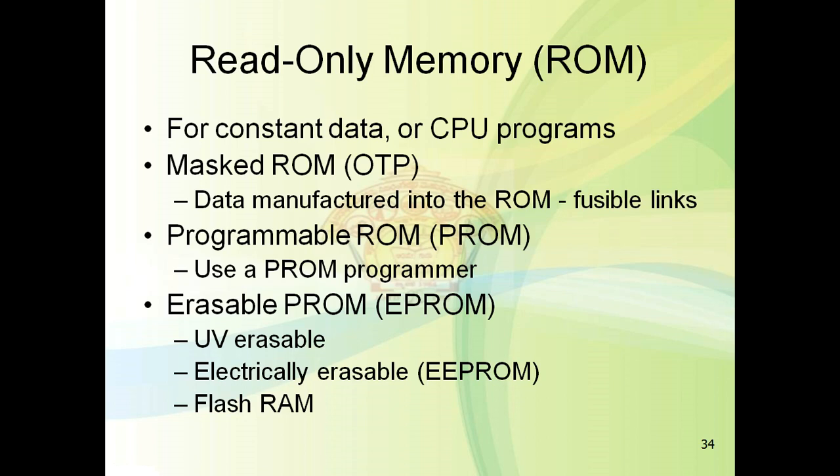Okay, we can erase line by line, we can erase word by word in case of electrically erasable programming. Another type of memory is flash RAM. It is again by using NAND transistors and NOR transistors, or by using NAND and NOR technology. So they are erased by block, okay, and hence this type of memory is called flash RAM.